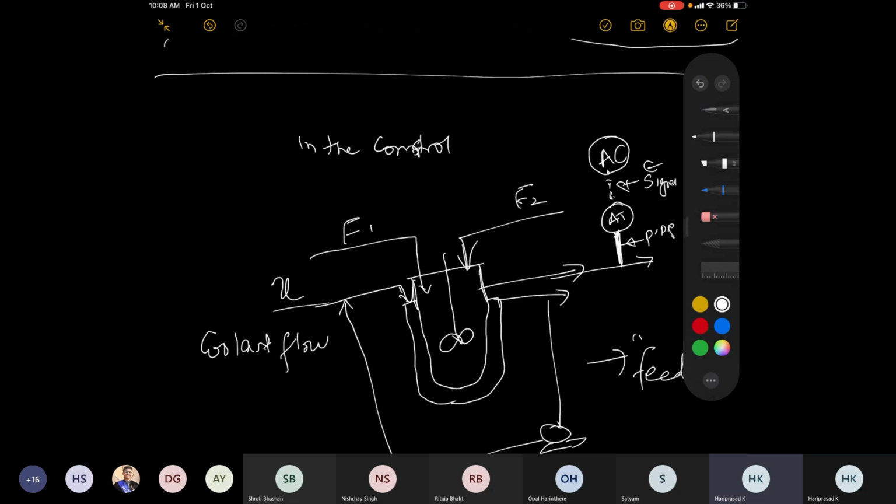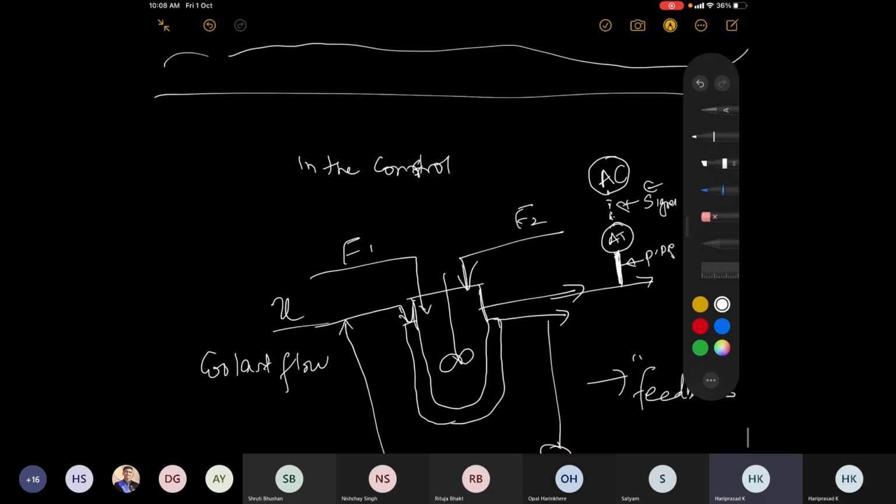This analyzer controller you would feed with the desired value, which is your set point. Based on the current value received and the set point given, it computes the error and the corresponding control action, what you need to do. Eventually it produces a signal that helps you to course correct.